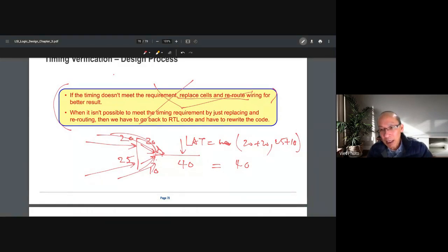But the answer for now I got it. The answer for the signal wire in VLSI: we don't do the shield for the signal. We only shield for the clock, because clock is crucial, right? It's the heart of the chip. So we have to protect the clock integrity, signal integrity to the maximum. That's why for the clock, we shield it from the root down to almost more than half of the clock. But the signal, we don't.